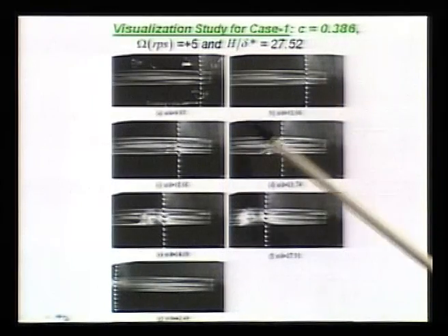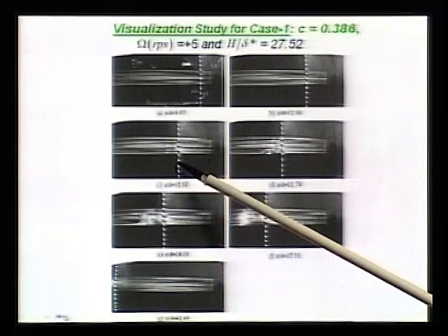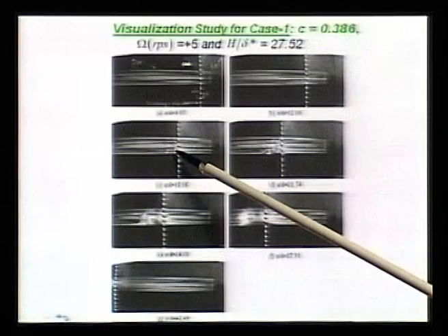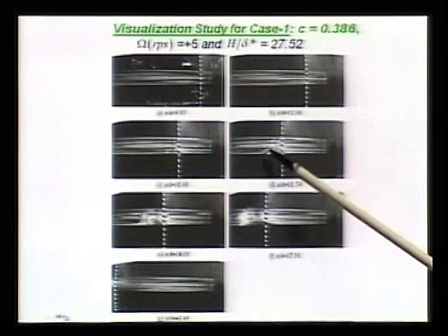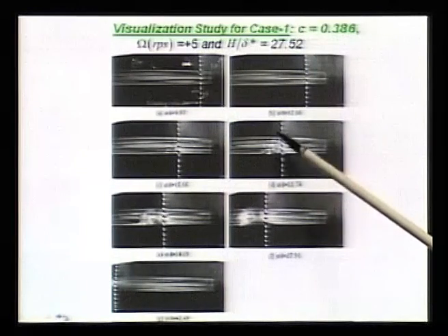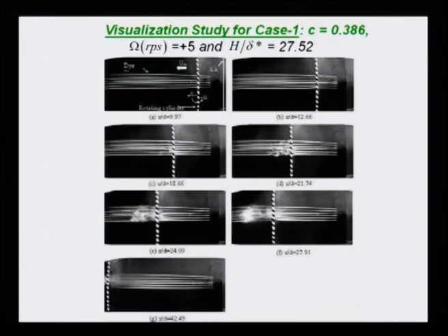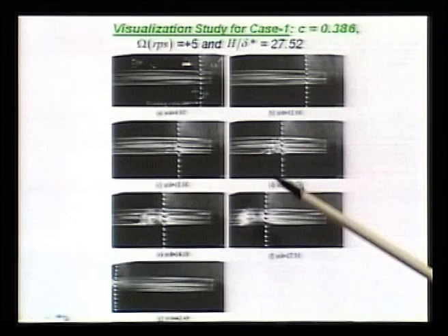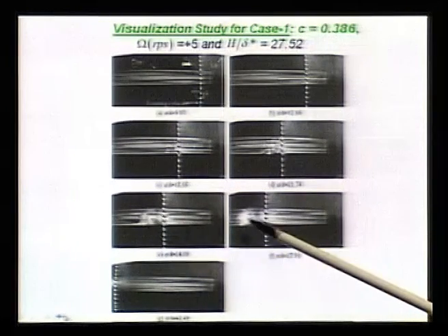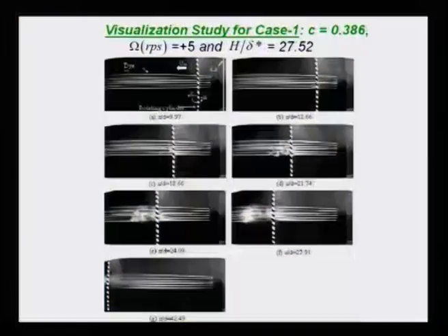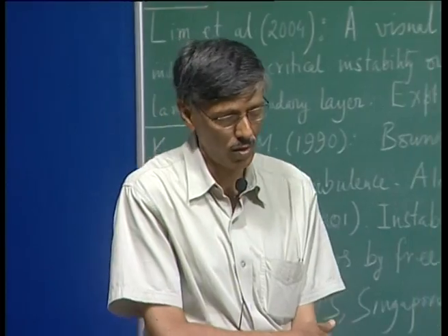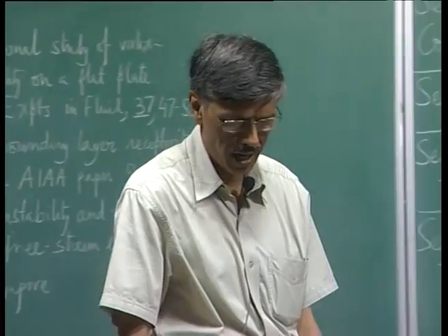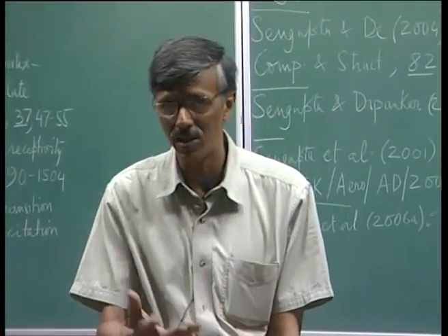However, sooner or later it starts picking up, and once that primary instability sets in, that in turn leads to secondary and tertiary instabilities that are manifested here by rapid diffusion, mixing, and even the chaotic nature of the flow. That is what you see in subsequent frames. And the good news about this is when the cylinder is crossed over, again you get back to your undisturbed flow.